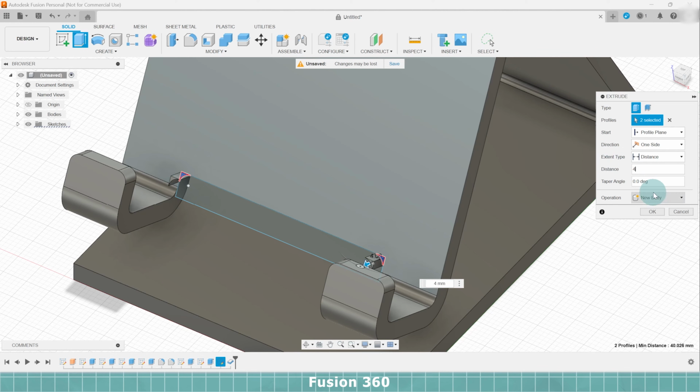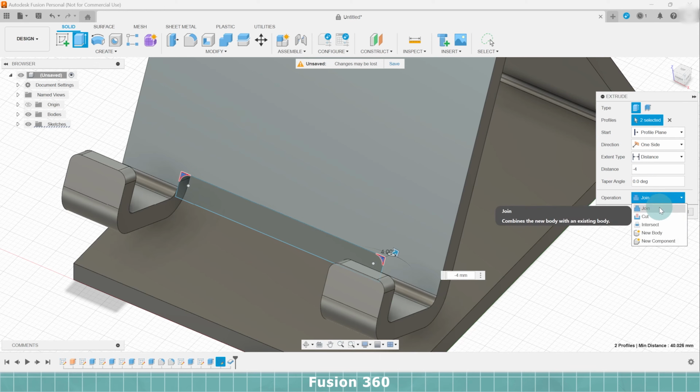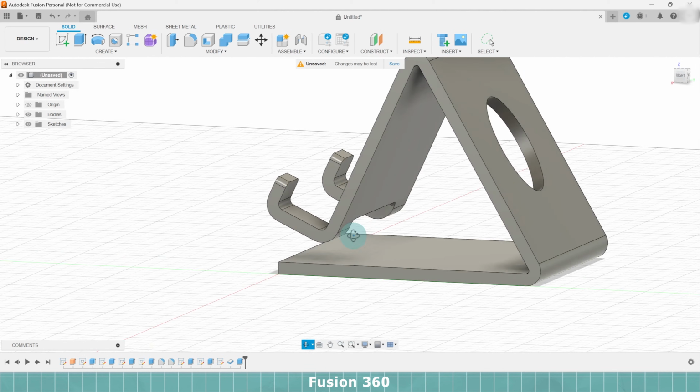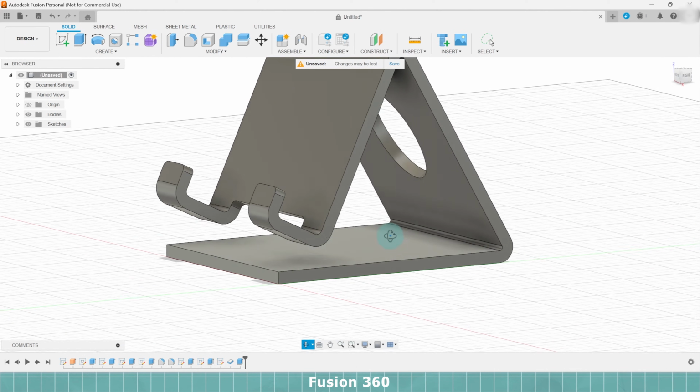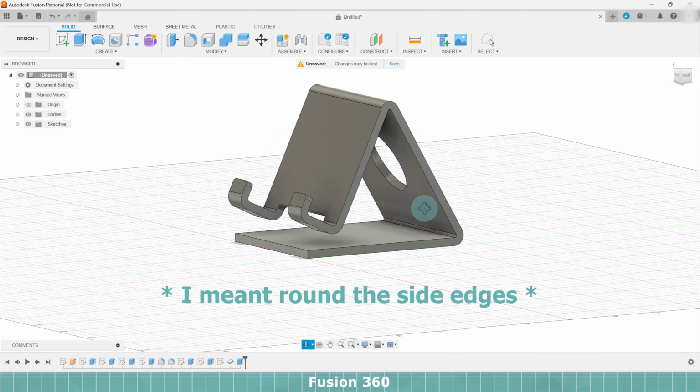So now I'll just jump back to the previous sketches that I've done with fillets and extrude them to round some of these remaining corners. One thing that bugs me a bit is that the base is no longer flush after thickening the model, so I'm just going to fix that quickly, then round the corners. Feel free to skip this part though and just round the corners if you like.